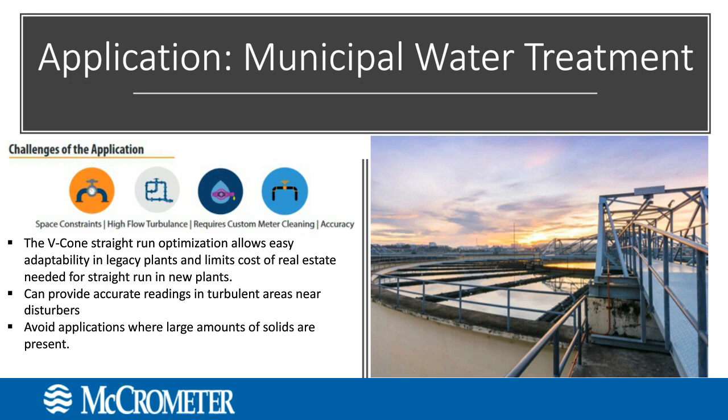We want to avoid applications where there are large amounts of solids present, just simply because of the way that the pressure ports are done. Solids have a tendency to clog things up. So we want to stay away from any solid effluent applications within the water treatment plants.